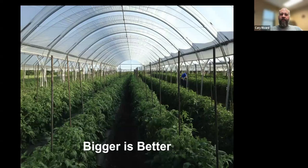So in general, when we're talking about thermal mass, really bigger is better. And it's important to recognize that there is such a thing as too big of a high tunnel. This is a 1 acre high tunnel that's out in Kingsville, Missouri at Powell Gardens. This was 11 bays of a multi-bay tunnel. This is a very serious high tunnel. But the bigger that tunnel is, the more heat it's going to be able to hold overnight. And again, what's equally as important is the slower it's going to warm up in the morning and in the day as well.